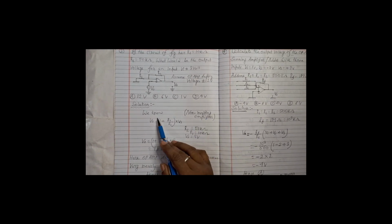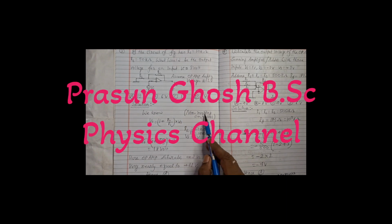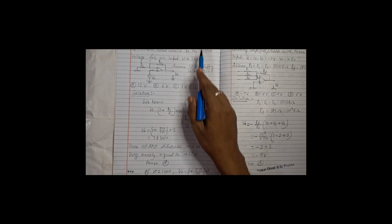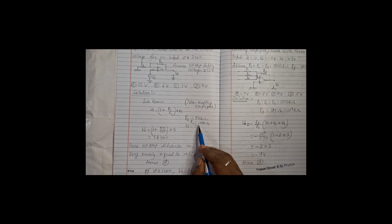So solution, we know that V0 equals (1 plus R2 by R1) into Vs. Here the op-amp acts as a non-inverting amplifier. So this is the relation between input and output in case of a non-inverting amplifier. R2 is given, that is 50 kilo ohm, R1 is 10 kilo ohm, Vs, that is input voltage, is 3 volt. Putting the values in this equation, we get V0 equal to 18 volt.